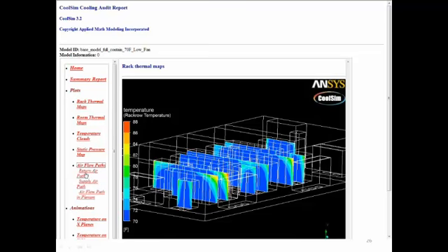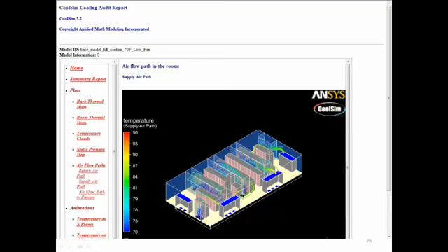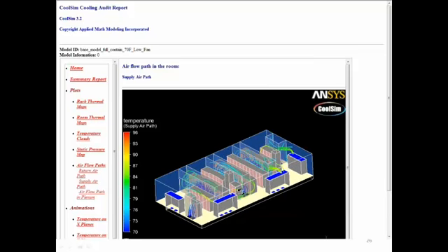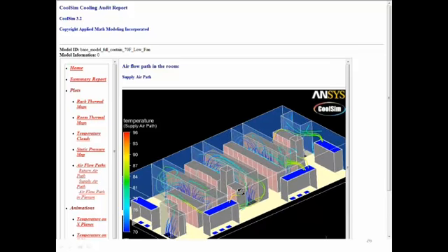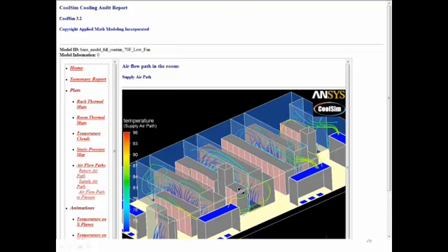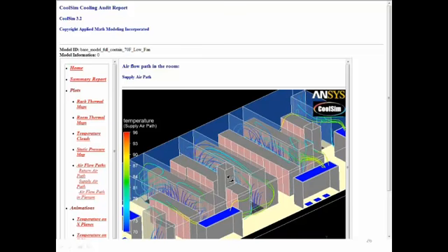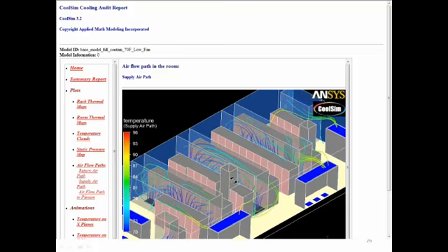And you'll see here on the return side, well, let's do supply side. On the supply side, you'll see much fewer path lines because now we're matching pretty well. We're matching demand versus supply pretty well, so you get a nice even distribution and very few path lines coming back. So the room's in balance. By the way, the room will be quieter.